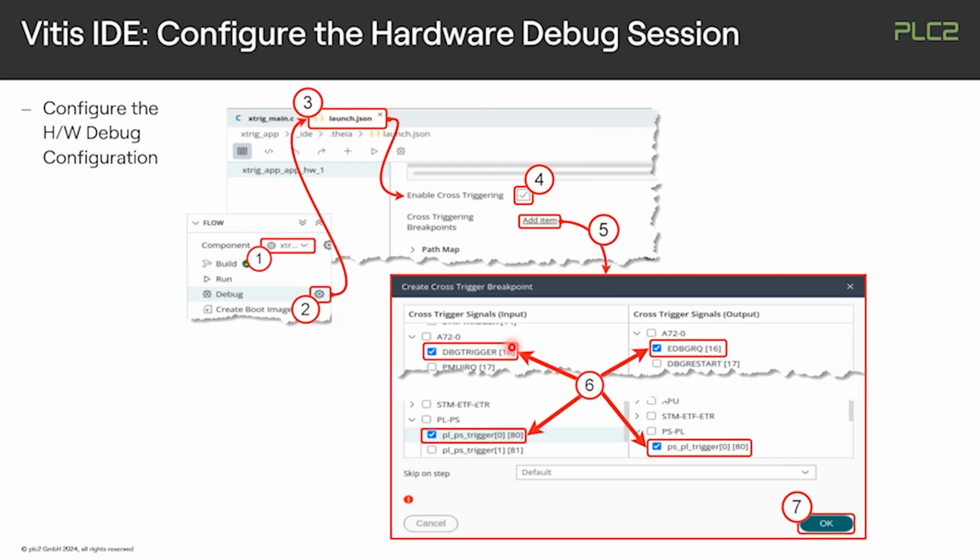So that's the reason that in this case, for the one CPU core, both directions of trigger in and trigger out are selected. That's these both, and two signals in the connectivity with a programmable logic. So very reasonable. 4 instances need to be enabled, but you can have even more or less, just as you like.